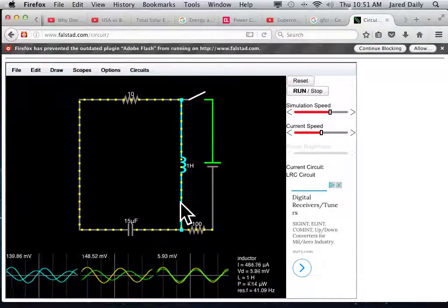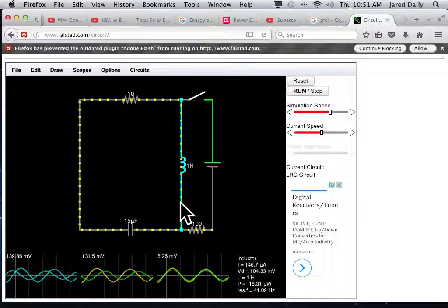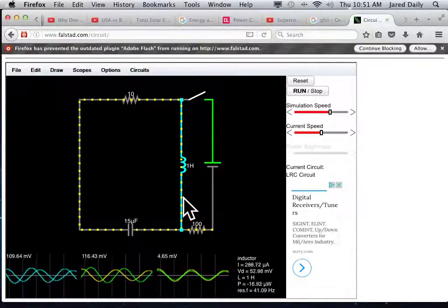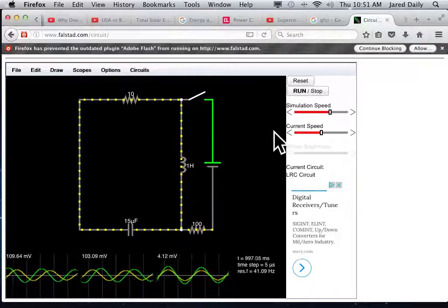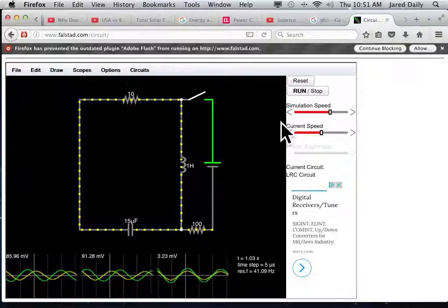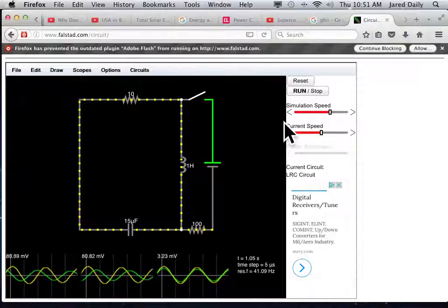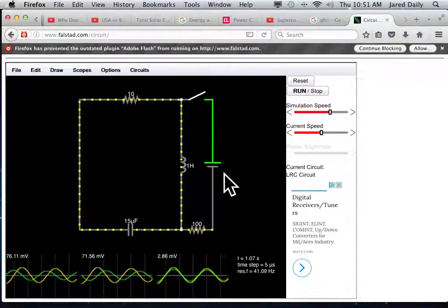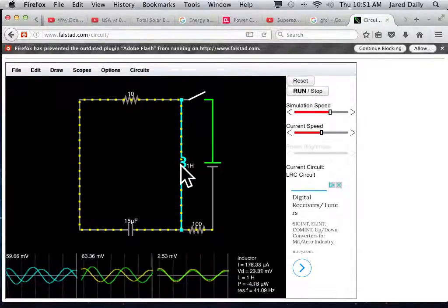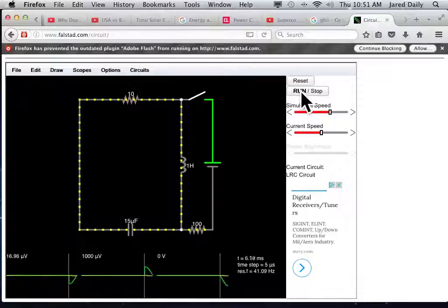If they're kind of in sync with each other, pushing and pulling, then you can get a maximum amount of current. But that can only happen if we can get these things at the right frequency. The frequency has to be correct, or the size of them has to be correct. So we adjust the size to correspond with a particular frequency, and then we go out there and look with that frequency.